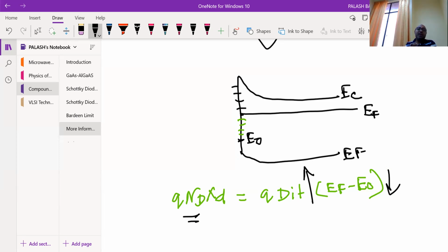But the ultimate thing is that it is talking to interface states, and since it is talking to the interface, band bending can already happen, everything is fixed. Since it cannot see the metal, whatever you do, there is no charge exchange, and since there is no charge exchange, EF is kind of fixed over there. Okay, so I'm stopping there, and this is the end of the Schottky junction diode.